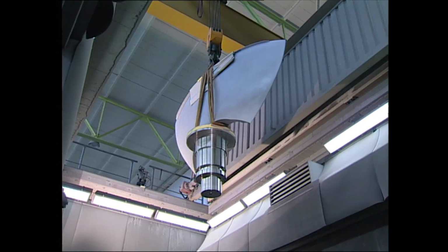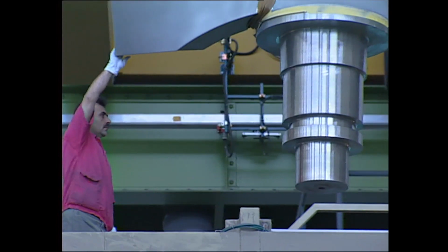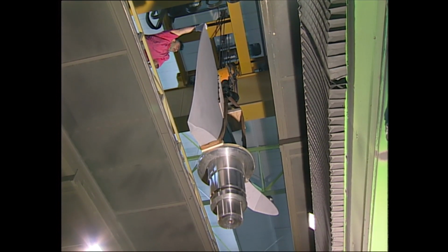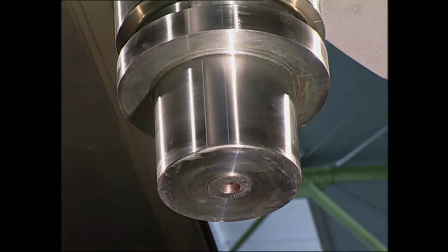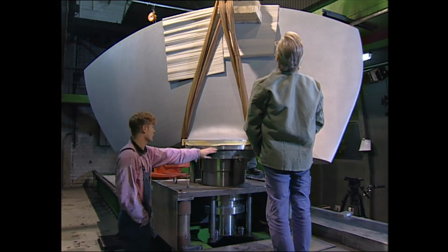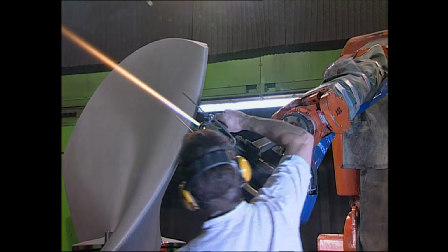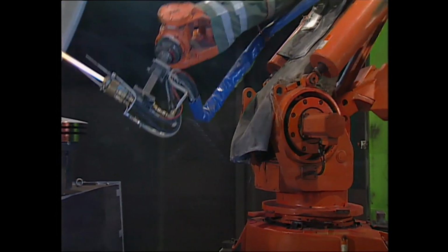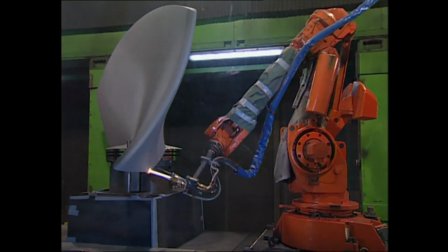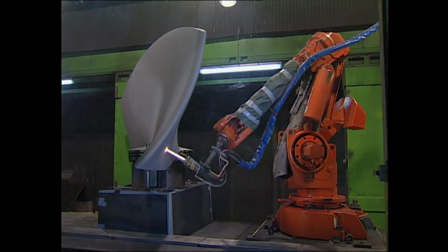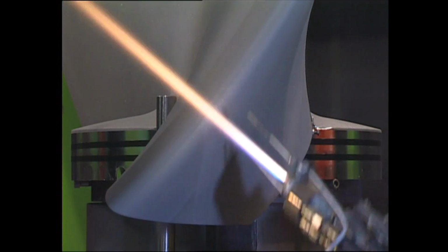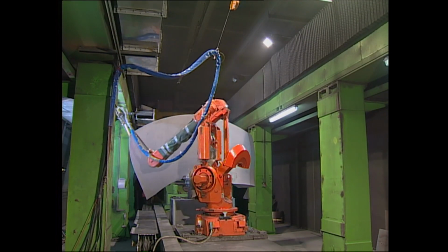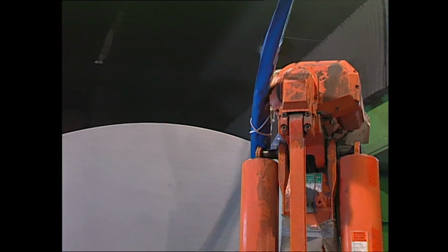The environmental conditions have to be closely controlled during the coating process. Noise, radiation and dust emission restrictions mean that the coating has to be applied in a suitable spray box. The distance and angle of the spray gun to the workpiece and the relative gun velocity must be kept within narrow limits. The coating of three-dimensionally curved surfaces, such as turbine blades, therefore requires the use of robot methods.